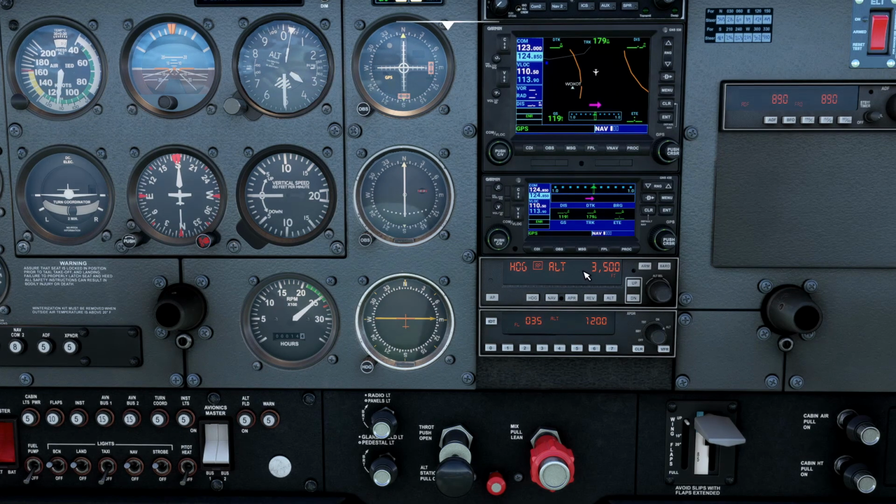One little caveat about using the vertical speed and altitude pre-select mode is that if you are at the altitude that is in your altitude pre-select window and you go into vertical speed, it oftentimes will not initiate a climb or descent. Basically, the system immediately captures the altitude because it's at the altitude in the altitude pre-select window. It says, hey, I'm already there, and captures it, going back into altitude hold mode. So if you want to initiate a climb or descent, you need to have something other than your current altitude, preferably at least a few hundred feet away from your current altitude, in this window.